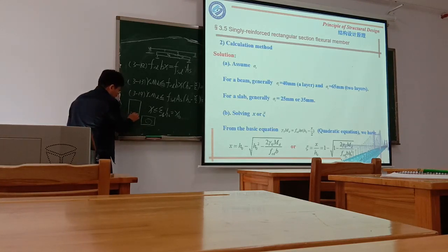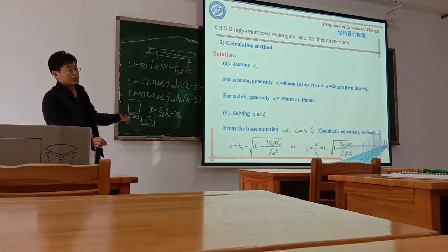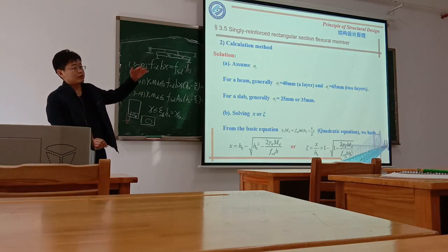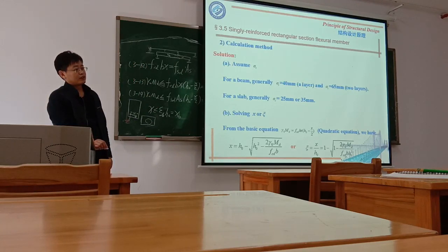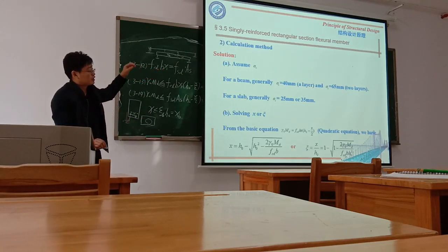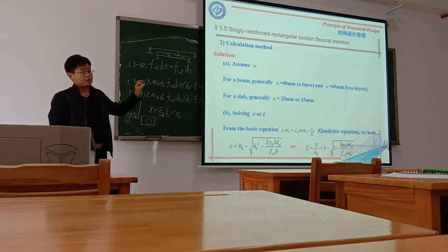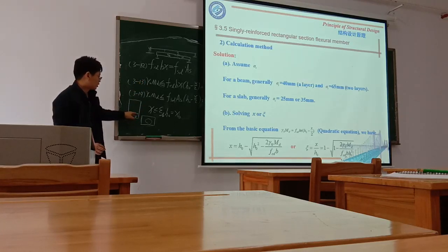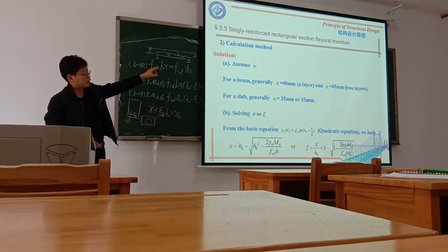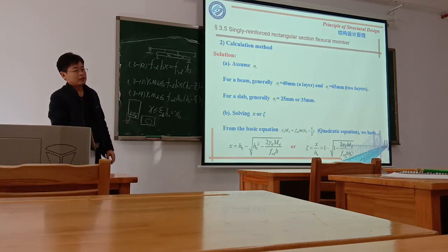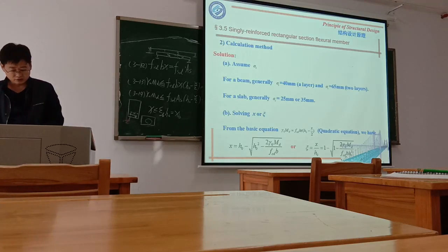we have introduced how to calculate AS for the center of the steel. For one layer it is easy. For two layers, or three or more layers, you should know how to calculate AS. Because at the first step, we just assume AS. Once you determine the reinforcement ratio and then you put the steel inside, you have to calculate the real AS and compare it with the value you assumed, to check if it's okay or not.